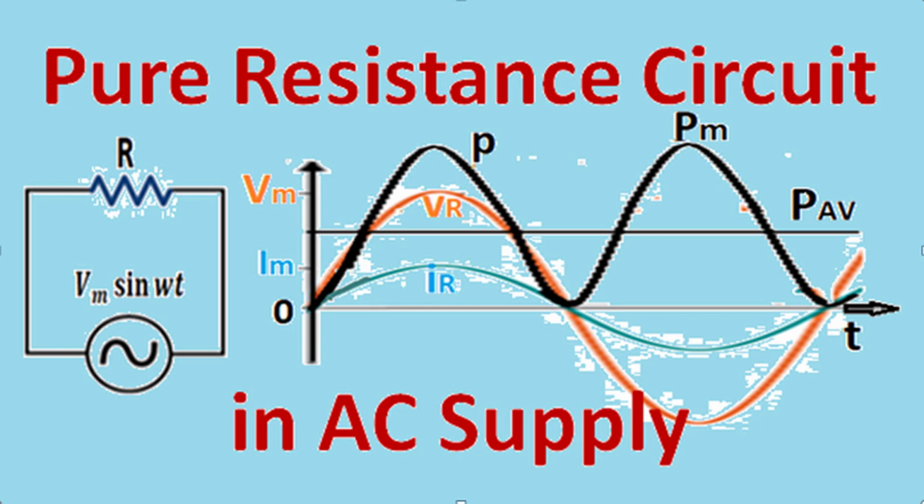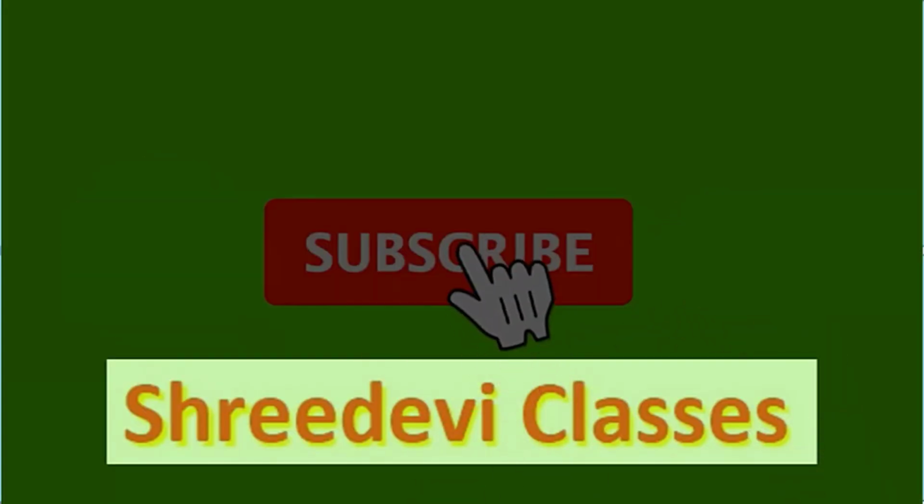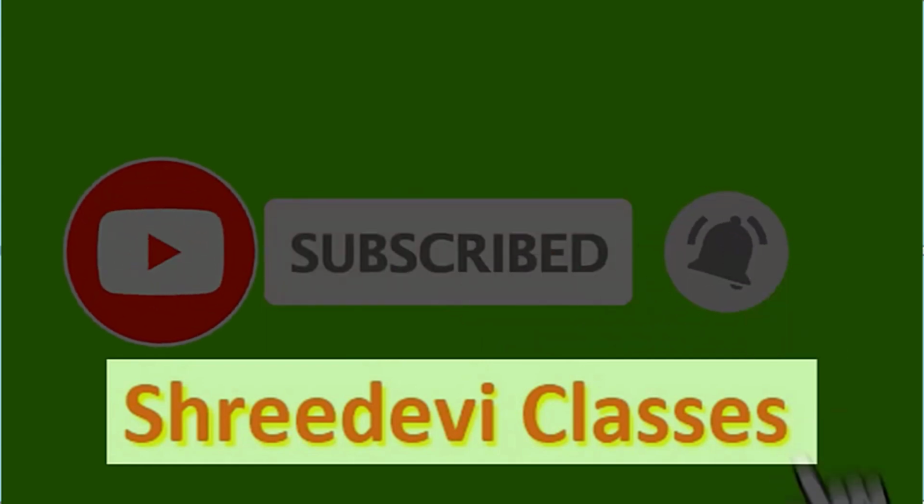Today in our playlist Basic Electrical Engineering and Class 12th Physics, in our chapter Alternating Current Circuits, we'll study the behavior of pure resistance in alternating current supply. We'll soon find that in a resistance circuit, when alternating voltage is applied, an alternating current of the same phase will result, and in those conditions there is always flow of electric current producing heat energy, and power is fluctuating but always positive. That means electrical energy always gets converted into heat energy.